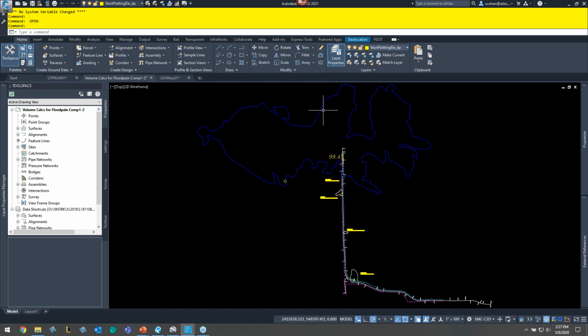Again, if I'm already above the floodplain, you don't need it. But if your job is below the floodplain and you're filling in those areas, that means borrow, then you need a compensation pond. If your job is in the floodplain and you're literally cutting out the earth, they don't care. It's fine. You're actually creating more room for water to be stored in that floodplain area.